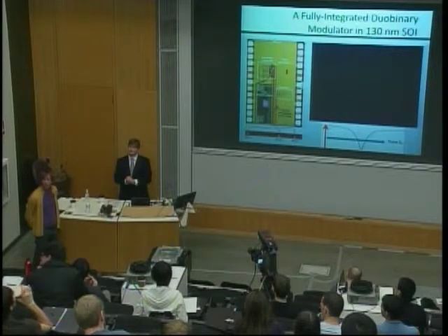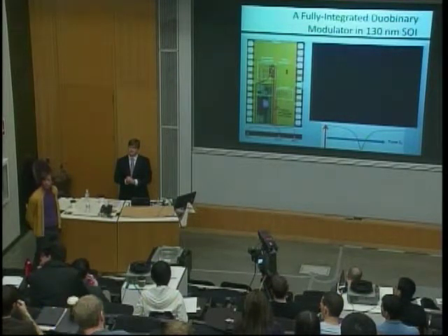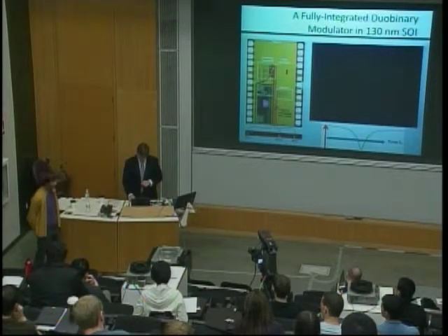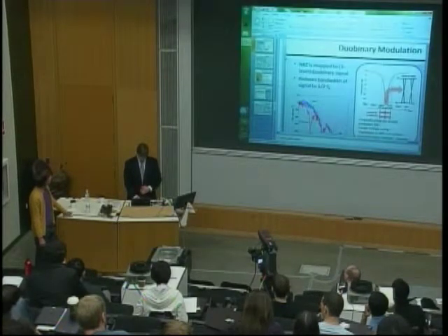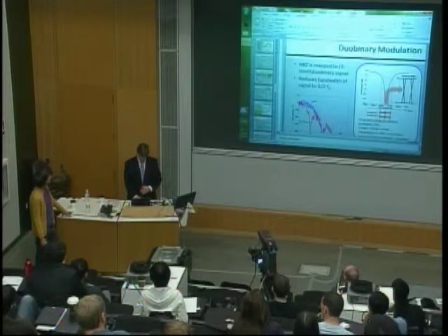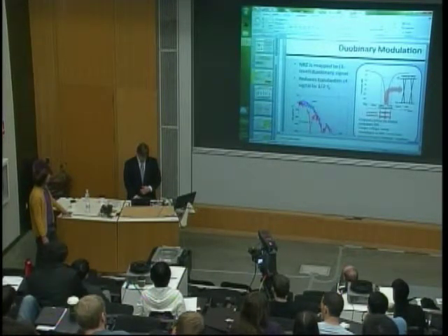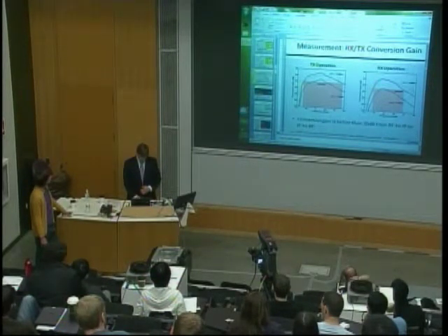So in the amplifier where you were using the positive feedback, I guess the natural question would be, how do you guarantee stability over process, voltage and temperature? I would think the stability is pretty well guaranteed because you're going to have difficulty getting gain at those frequencies, but how would you control the gain? I think that is probably the more practical question. Stability is probably not an issue.